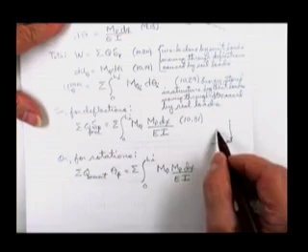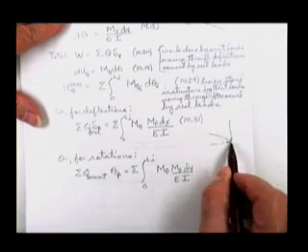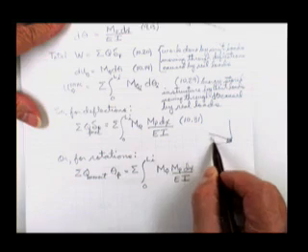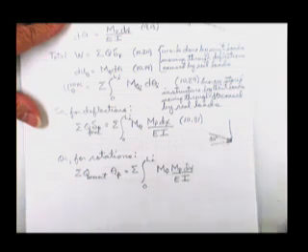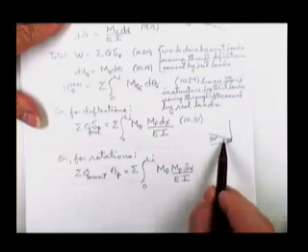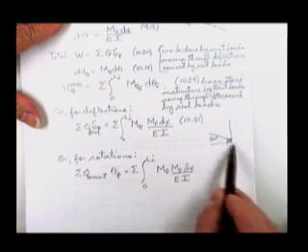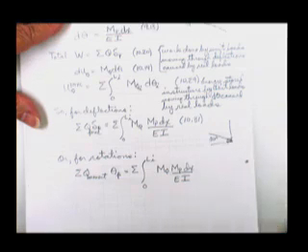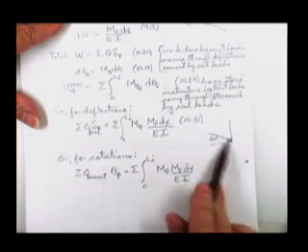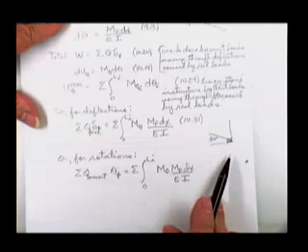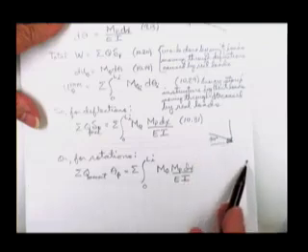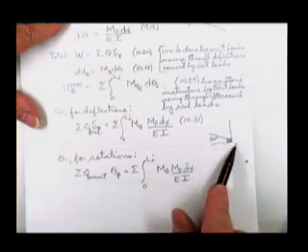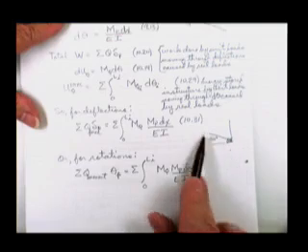If you want to know the deflection of that point at a 30-degree angle, then you put your unit load on there at a 30-degree angle, and when you get an answer, it would tell you the displacement of this point to some new location in that direction. And if the answer came out minus, then that means that the point didn't move in the direction you put the unit load, it went the other way.